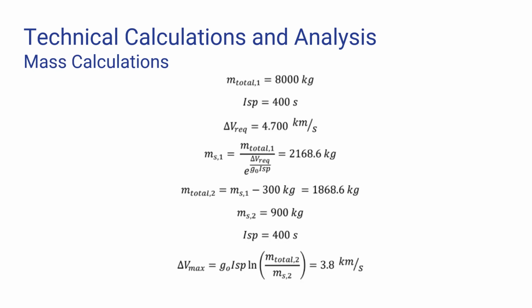Using the total delta V gained from the previous calculations, it was decided a two-stage design was necessary. In order to obtain the required delta V, the spacecraft stages before ascending from Ceres in order to cut down on structural weight. The starting mass of the spacecraft was 8,000 kilograms, which is the maximum the Falcon Heavy expendable can send on an energy orbit with a C3 of 33.5. This includes the mass of the second stage, which is 1,800 kilograms.